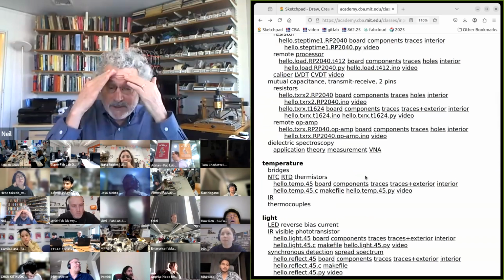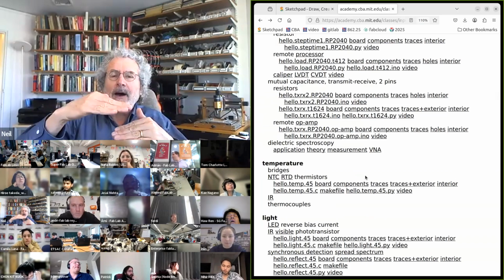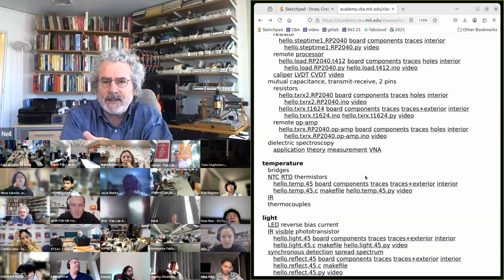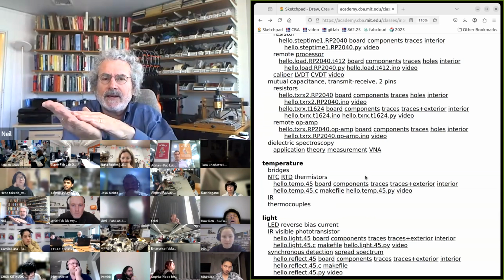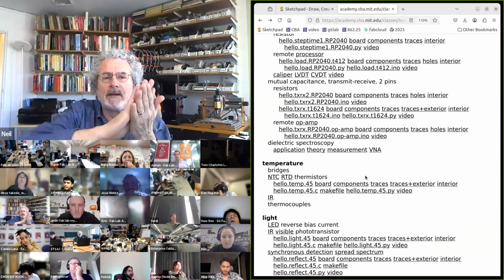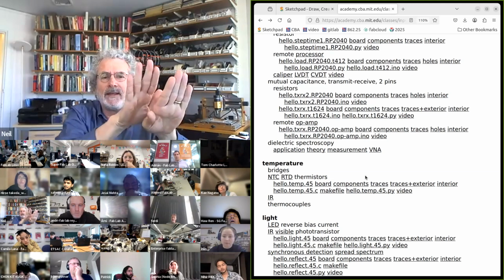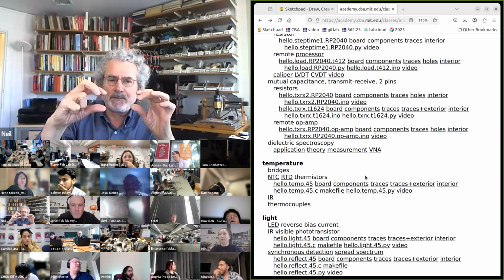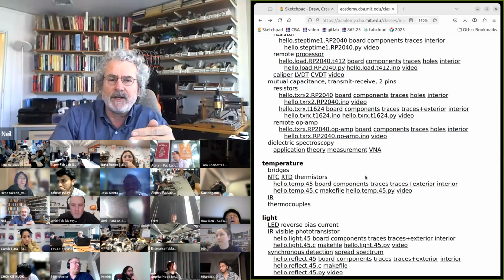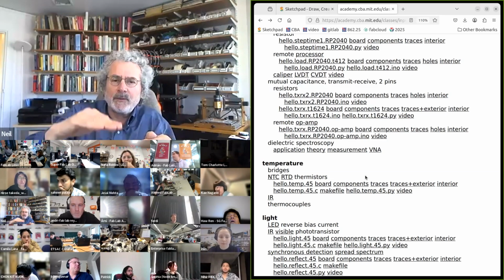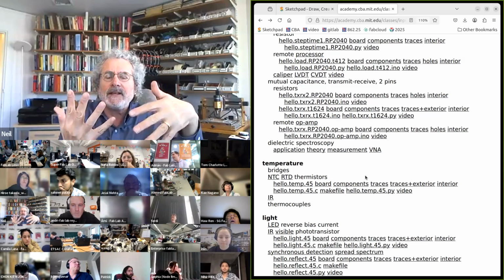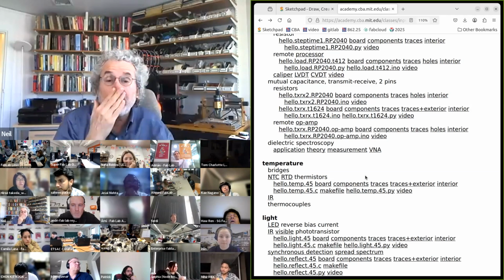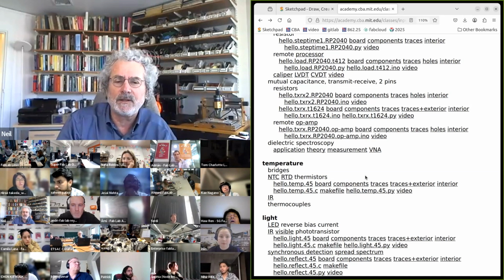So with that measurement, you can make a button, but the button isn't mechanical. It's just a sensor. You can sense through a case. You can make a force sensor. You can make a slider knob. You can make a rotary knob by rotating capacitor plates. If you put a liquid in a tube, you can make a tilt sensor. If you put it around a container, you can measure a liquid level as the liquid comes in. If you make a rigid electrode and a flexible electrode, when you move it, you can measure their distance. And from that you can measure acceleration.